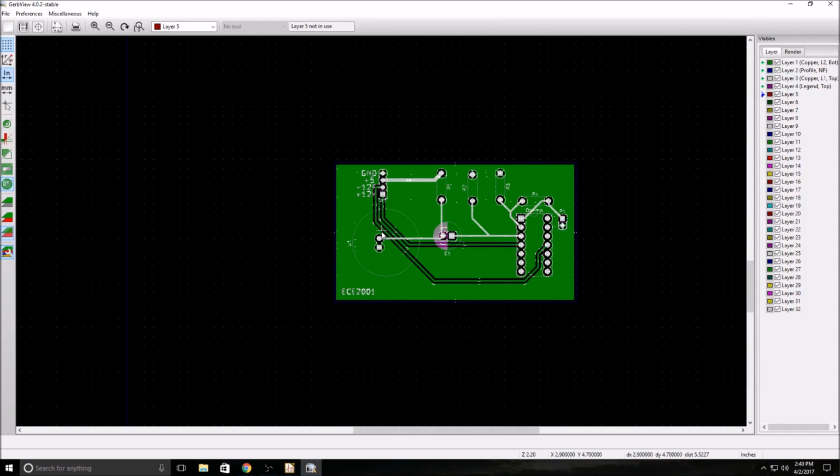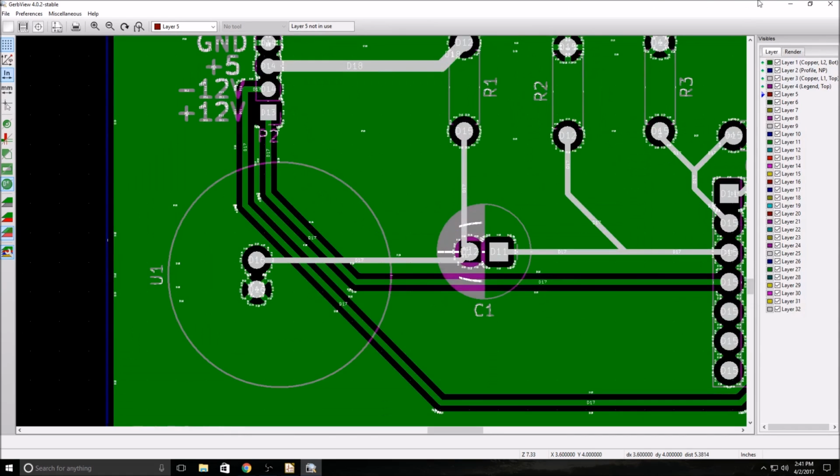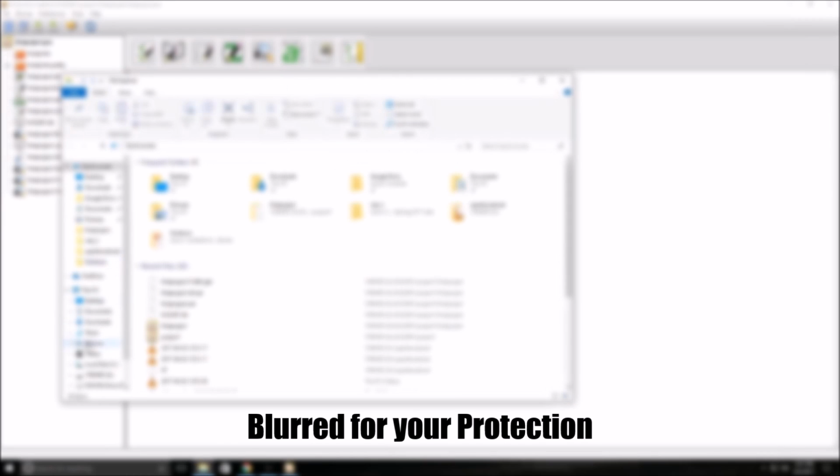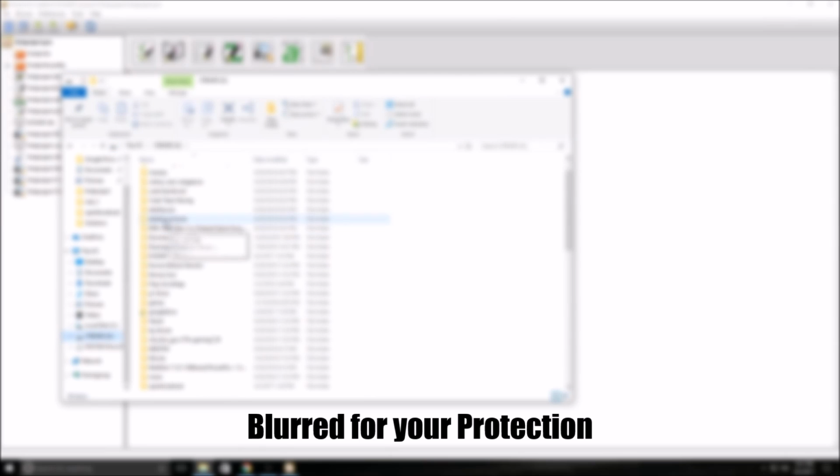If everything seems okay from here for you, then you can copy all of those files, which we'll look at real quick. All of these, make sure that you have all of these. We'll put this into a nice folder. Call this Gerber, and we want to select all of the ones that we have. So the back copper, the drill stuff, the report. Now this drill file tells the machine where to drill. So we have the back copper, the drill, the maps, the edge cuts, the front copper, and the back silk.